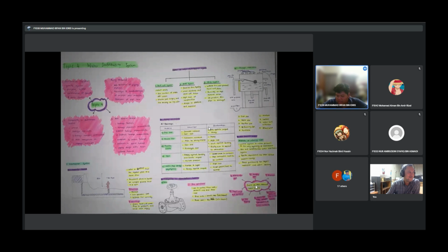So we go to the non-revenue water. The methods of reducing non-revenue water, that is control system to reduce pressure at the very beginning of distribution. The second one is new and comprehensive water distribution system. The third one is specific department for non-revenue water related problem solving. And the last one is strict punishment for illegal connection and water leaching.